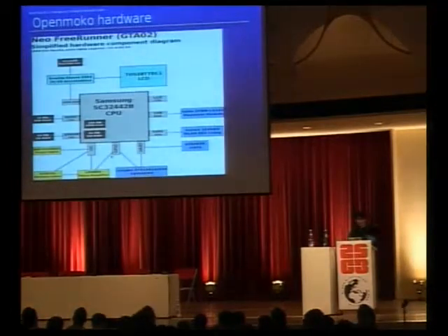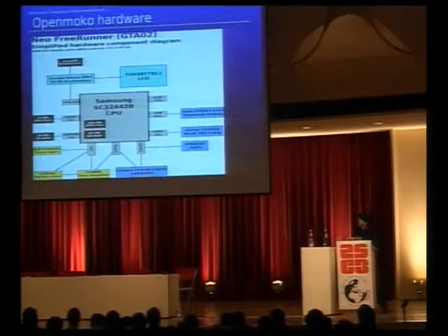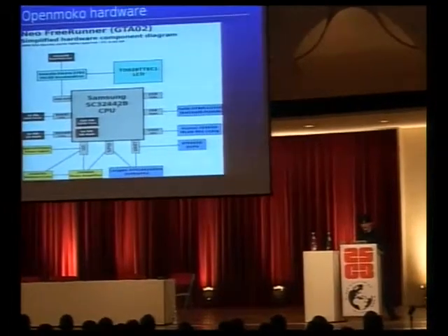If you look at it in a high-level, simplified diagram, how all this looks, basically you have the system on a chip in the center. In this case, what is used here is from Samsung. Sometimes they call it S3C, sometimes they call it SC3. They don't actually know which one it should be called, so don't be surprised by that. This particular component is one component that is 13 by 13 millimeters, and I think maybe 1 millimeter in height. I don't remember exactly.